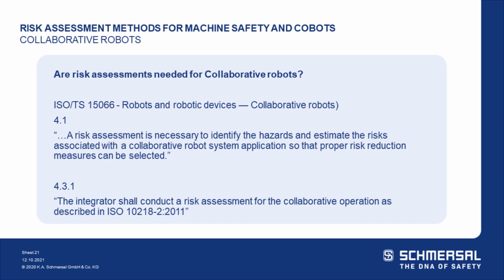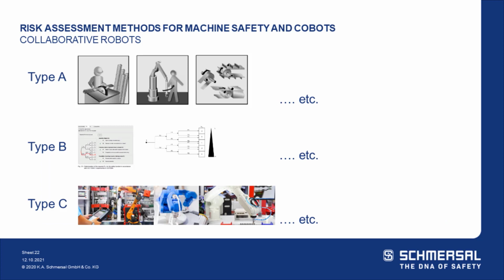On the screen here, you'll see that the Type C collaborative robot standard says yes, risk assessments need to be done. I will explain what a Type C standard is on the next slide. The reason we wanted to bring this up is that many of us hear from time to time, hey, it's a collaborative robot, it's safe, we don't need to do a risk assessment on that part of our cell. There's a common misconception that simply because it stops when it touches a person, it doesn't need one, but it still requires a risk assessment. We hear time and time again that it doesn't, however, they do need to have a risk assessment done.